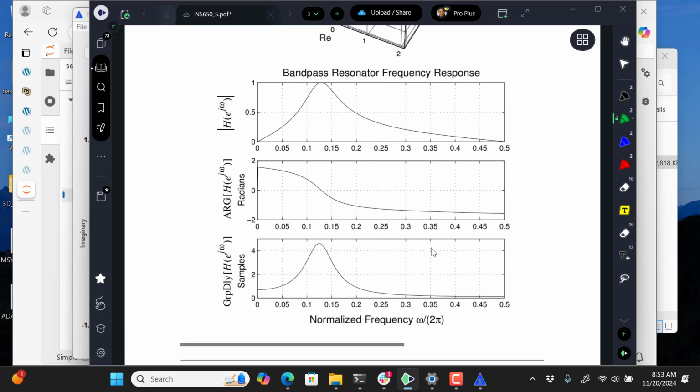There's the magnitude, there's the phase. My software doesn't show you the group delay, but that's just showing that this peak is going to get bigger and sharper and become more of a group delay annoyance right in the vicinity of the signal that you're trying to pass. If you're not worried about group delay, you could do this, but it's not advisable for a lot of the modern digital comm systems where you'd want to have linear phase.